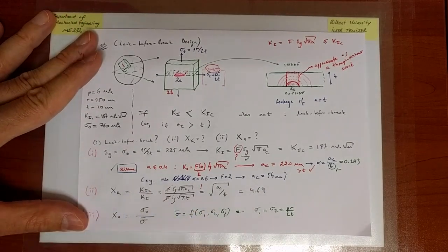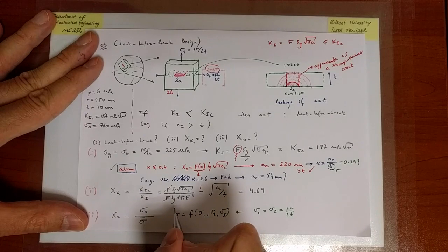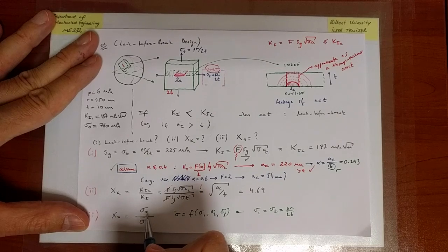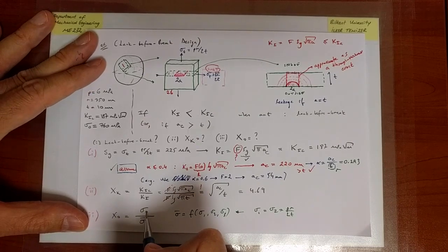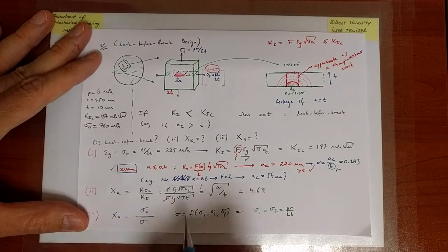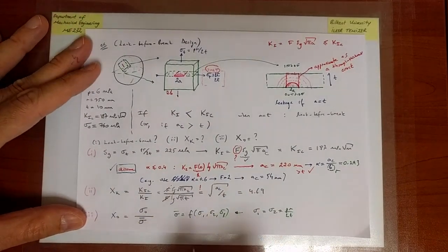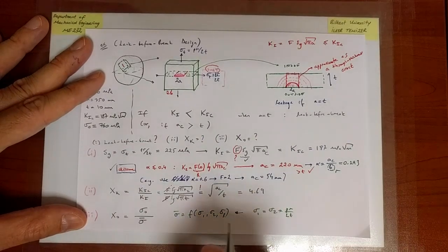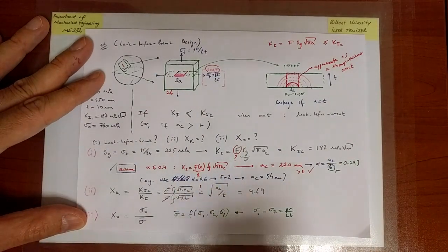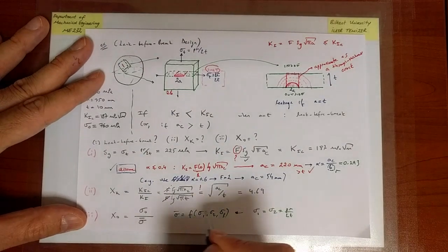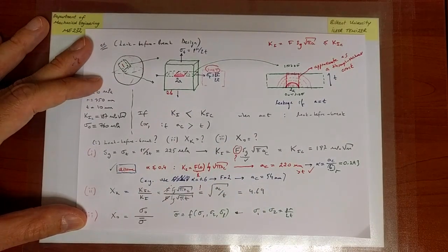But in any case, there is a limit on the critical value of the equivalent normal stress that we can go up to. Because it's ductile, because we're provided with a yield strength, we know that it's ductile, so I'm taking the critical stress to be sigma naught, and I'll scale it with some equivalent normal stress. So we will in general, remember, have a complicated three-dimensional state of stress. We convert it to the principal picture. The directions of those principal stresses don't matter. We are assuming isotropy always in the background, apart from our discussion of anisotropic elasticity. So those are fed into a function that delivers us the equivalent normal stress.